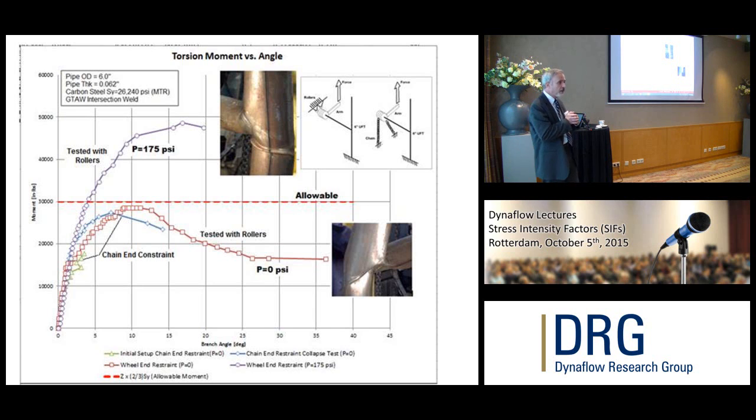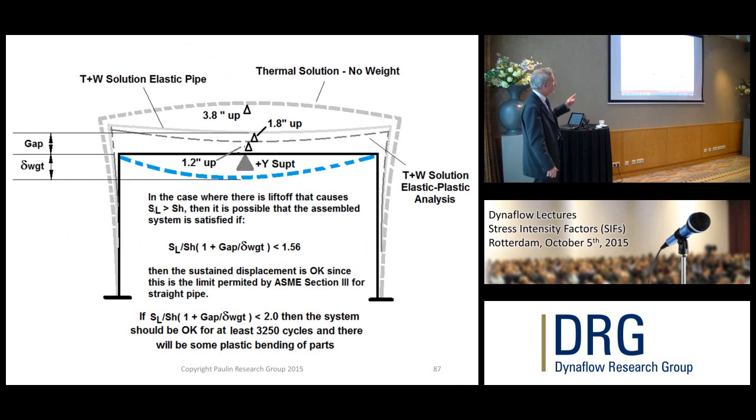I think it emphasizes the fact that it is important to use the right sustained stress index, 0.75. That's going to be important. But it's also important to know when a sustained stress is overloaded. When is it really overloaded? We don't have time to talk about these slides, but I'll give them to you.